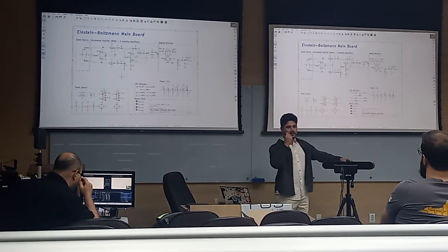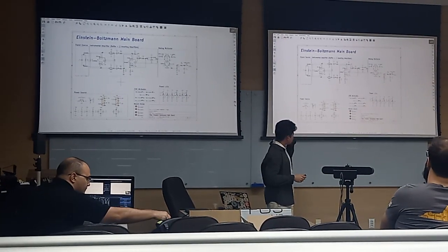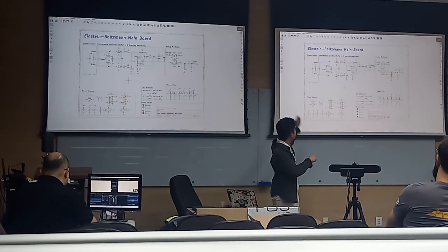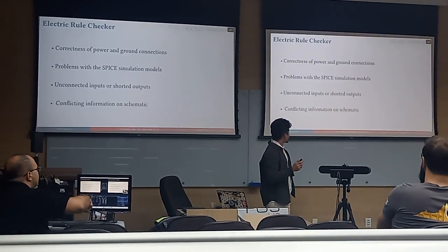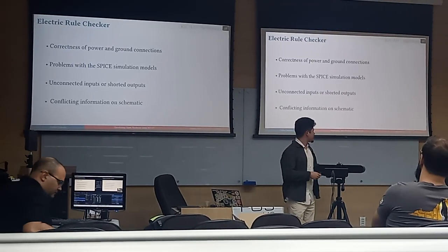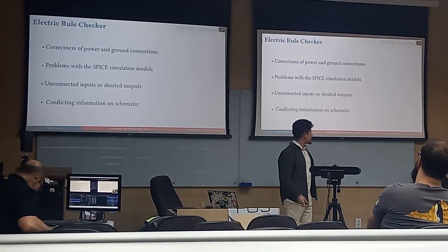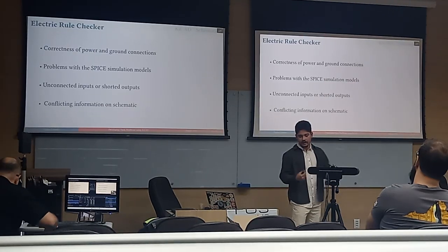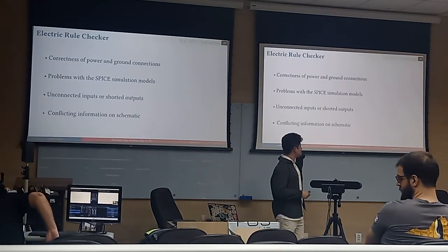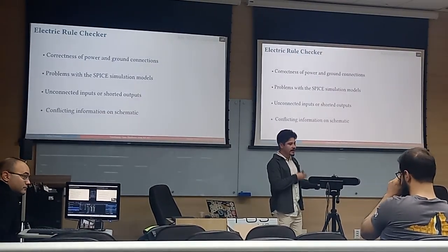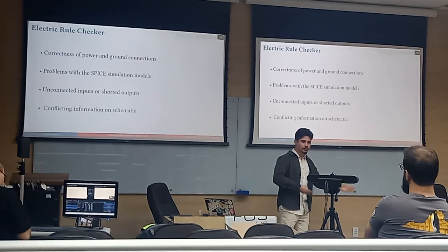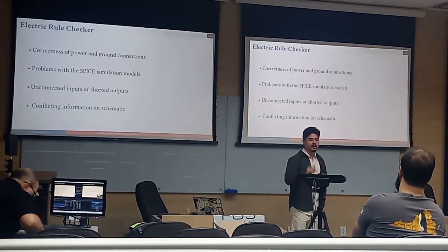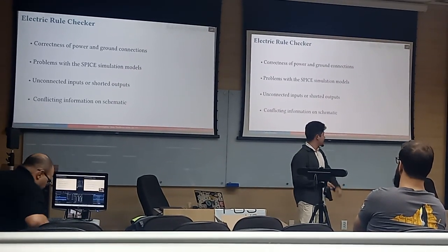It's not like you jump from one to the other. And yeah, KiCad is a very powerful tool to do this. You can make comments, draw things, and also one important thing: when you end your schematic, you need to check if it's right. So KiCad has a powerful ERC checker. This is common in professional tools, and I would like to highlight this because these are the points that I will highlight in the presentation that make KiCad, I think, a professional tool to work with circuits. You can, for example, check if you misconnected something, if something is unconnected, or if something is short circuited. It's a very powerful tool.